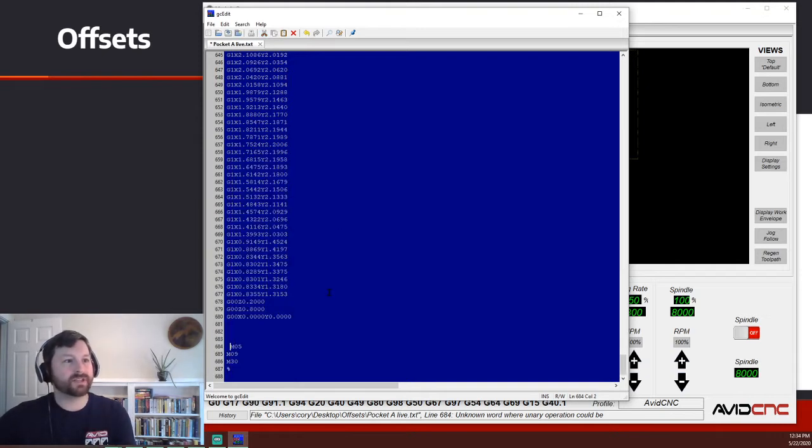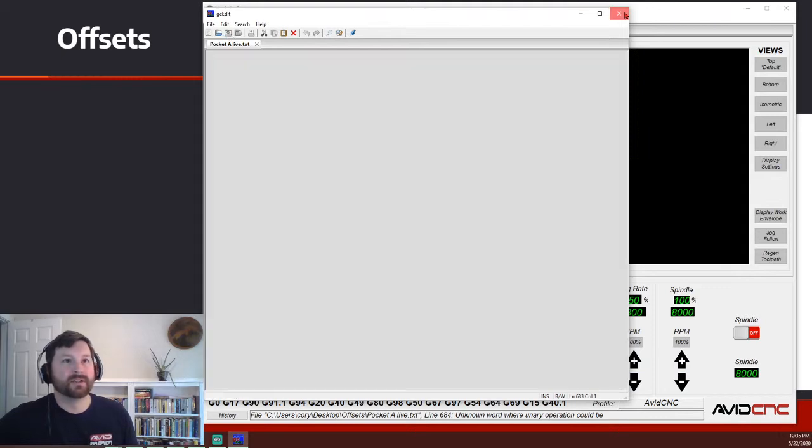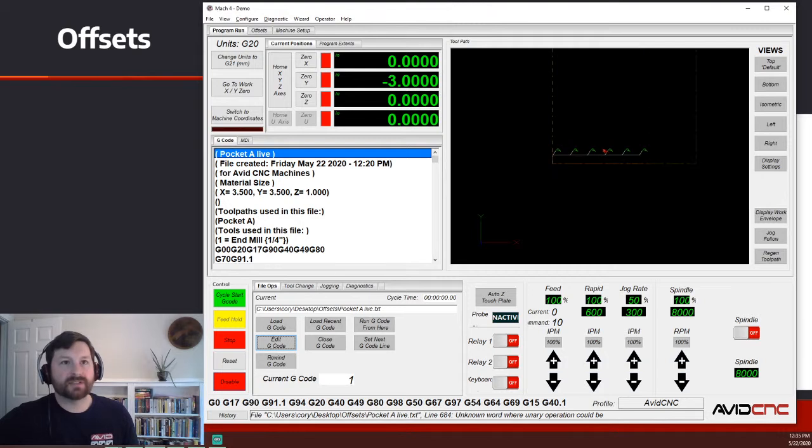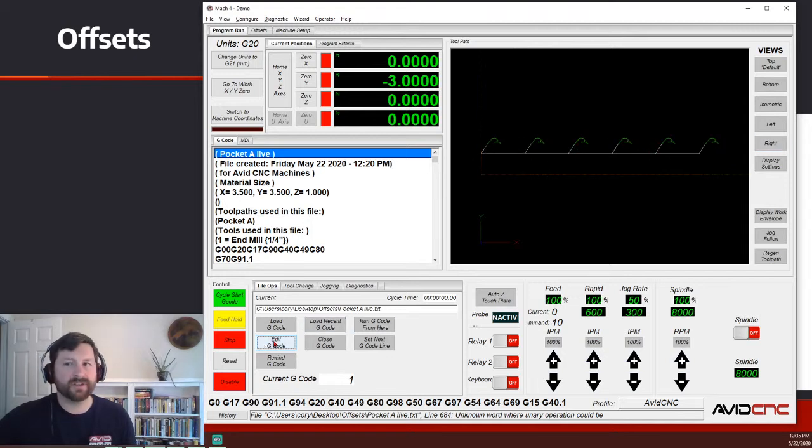So we're going to go ahead and delete that last G92 command that I had entered, and I'm going to resave this, and then I'm going to load it back in and see. Yeah, so it is that last G92 command that's corrupting my G code. Here you can see now we have the preview of those 6. So let me figure out why.